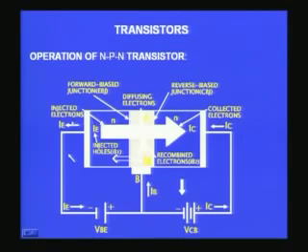So IE will be basically equivalent to IC plus IB. Some electrons are collected by the collector, some electrons find their way through the holes and back into the base region, and that corresponds to a small IB. So IB plus IC will be equal to IE.